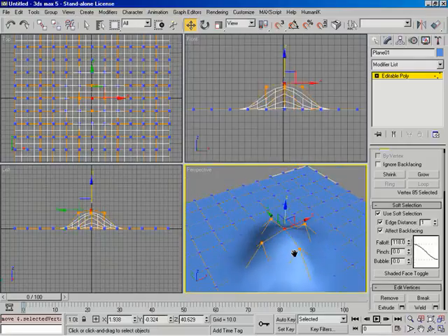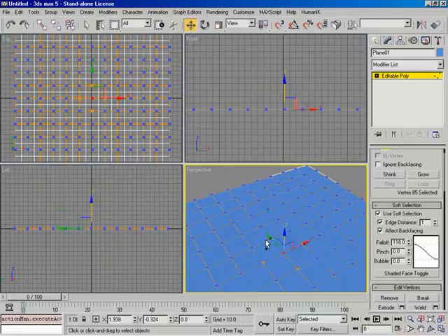Now, unfortunately, we have to look at our cage right now because I've got NURMS turned on. So you can see we're affecting one edge distance out, and then that's it. The effect's over. Okay. So it sounds kind of silly, but it's putting a cutoff on the fall off. Yes, exactly. The effect doesn't go out above that edge distance. So right now we're affecting one edge distance.